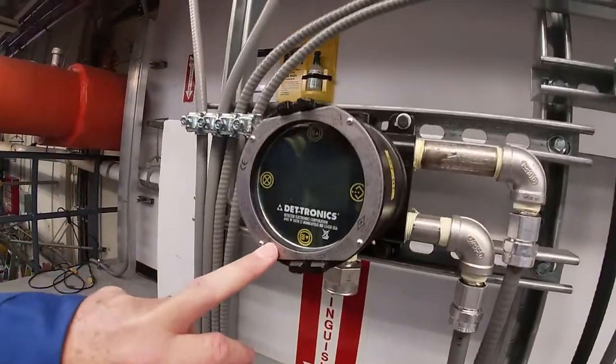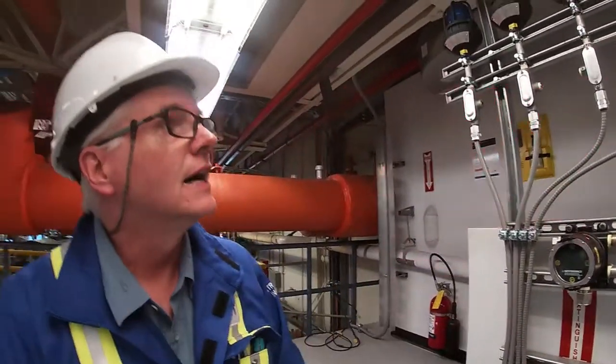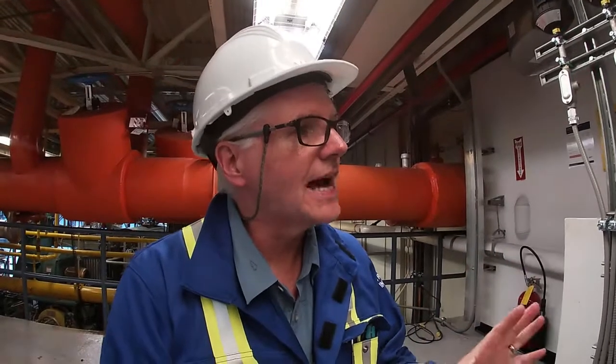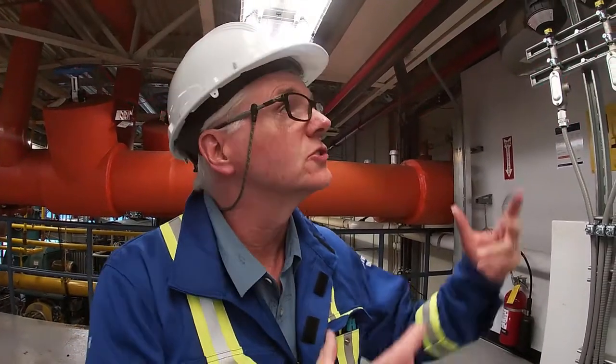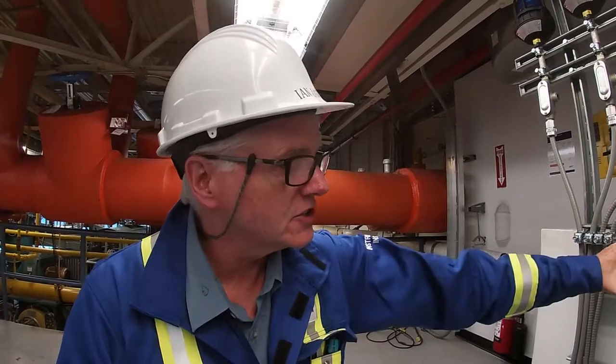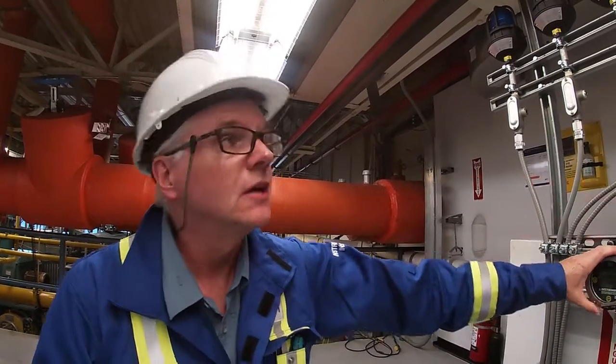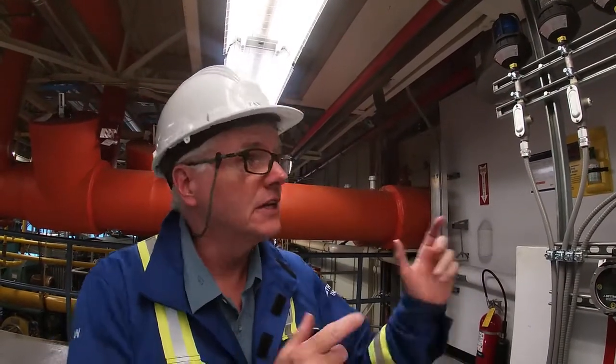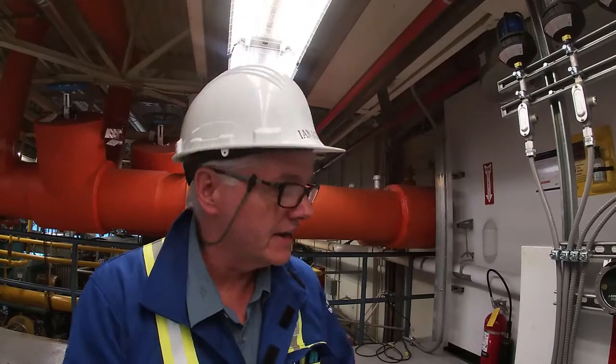Our trip was at 20%. We're way above. These have latched now. The reason we have them latch is because we want operations to come to the field and find out why this has gone off. Even if this comes back to normal, we still want to clear the area. All permits would be void, and we need to go and sniff the area and find out where this leak was, or if there was a leak.